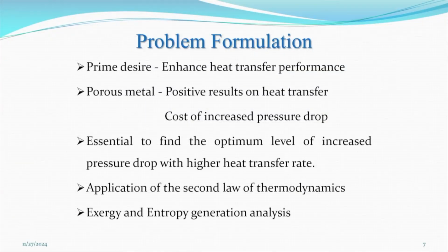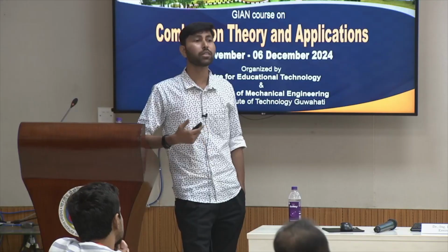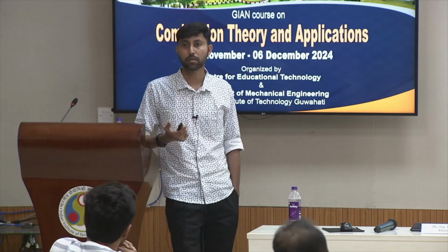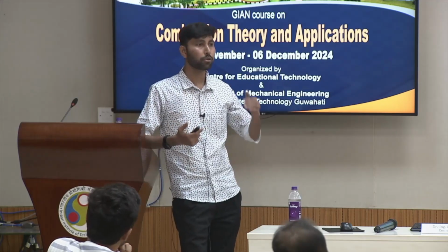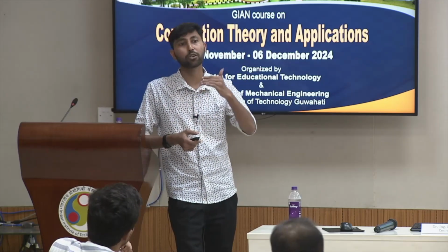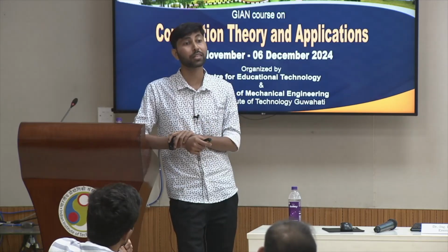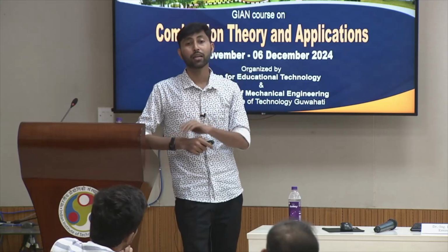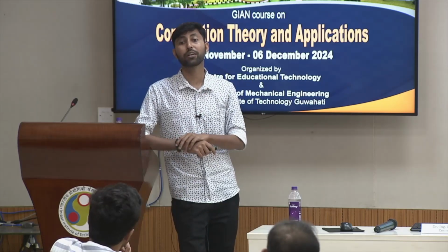So when we introduce metal foam in the heat exchanging devices, of course it will enhance the heat transfer performance. That is what we have observed in the literature also. But the novelty of my research work is that, of course it enhances the heat transfer performance, but at the same time when we introduce metal foam, it will increase the pumping power, meaning the pressure drop also increases, so that we can't neglect. The primary objective is to enhance heat transfer, but the increased pressure drop we can't neglect.